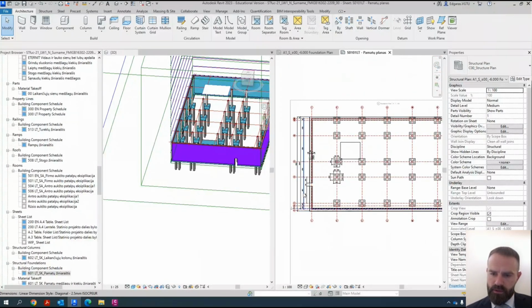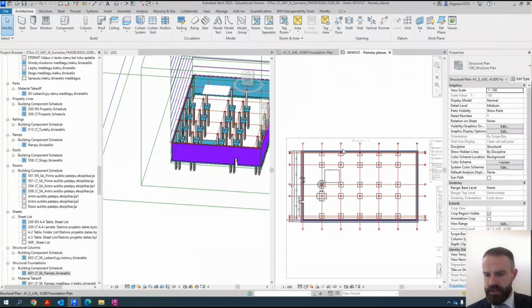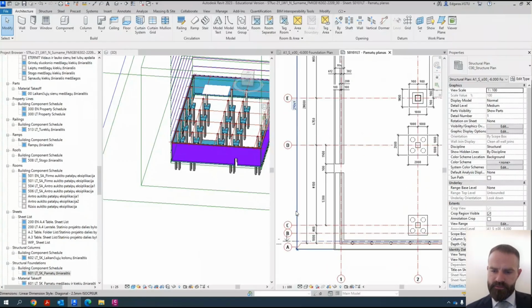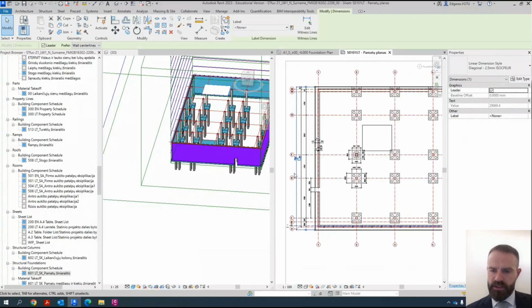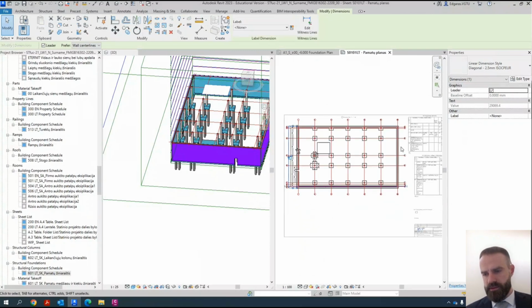And the same you should repeat on other side. If sides are similar, it's enough to put dimensions on one side. If the sides are different, it means the same dimensions go on all the sides. Of course, the total dimension of the building can be placed on one side because on the other side it practically will be the same.